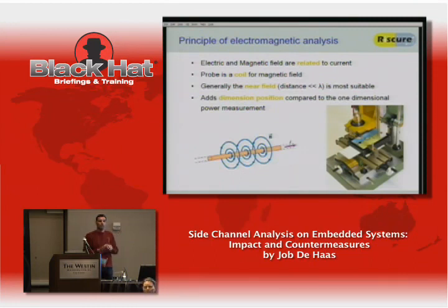It will be something that's a combination of all the small lines of signal that's on the chip that will create this field. And if there's only one bit that's interesting, it will have a little bit of influence in that field. Of course, there will be a lot of noise, but there will be a little bit of influence. And if you do sufficient statistics, like a big population of measurements, you will be able to find that signal in the noise.